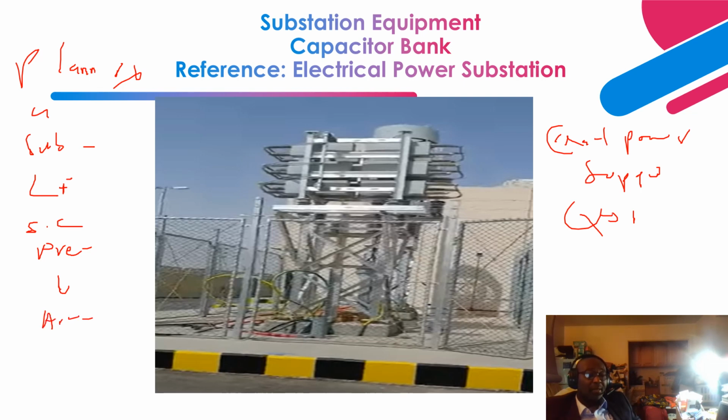Arc flash studies are usually done in that sequence: short circuit studies, protective relay coordination studies, then arc flash studies. And sometimes if you are in an industry that has large motors, then they perform motor starting analysis, starting the largest motor with the others running.